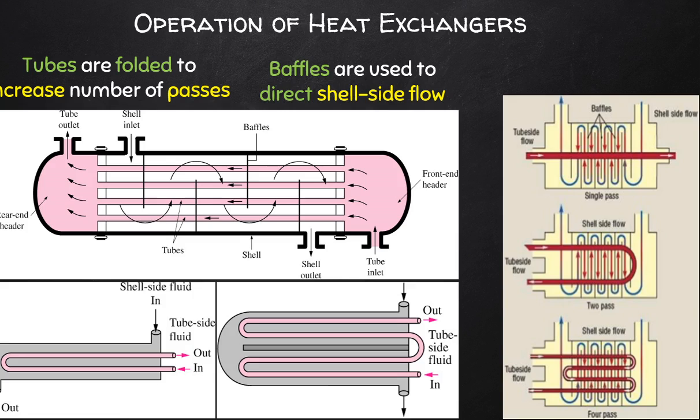The configuration here is shown in the horizontal layout, where the shell and tube is lying down. You can also design the shell and tube to be sitting upright, similar to what is done in nuclear reactors, where those are different designs. It looks a bit different, but it is a form of heat exchange design.